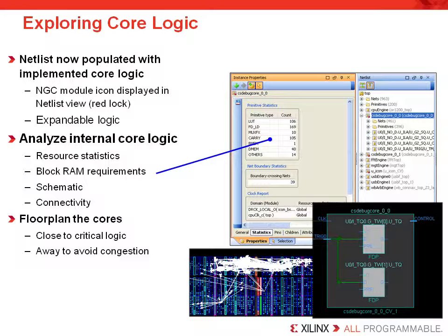One of the other side benefits of PlanAhead is the ability to make effective area constraints. Some customers choose to assign their ChipScope cores to specific area constraints in order to avoid routing congestion or to keep the core near critical logic. However, note that if you test nodes that are far away from the cores, then you can have some significant routing delay.